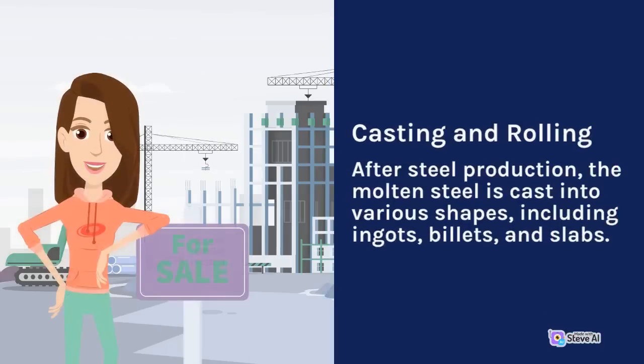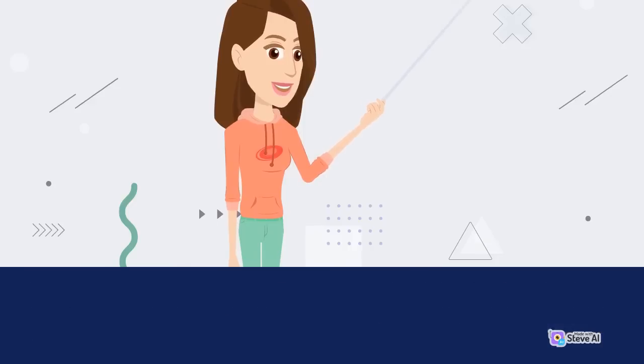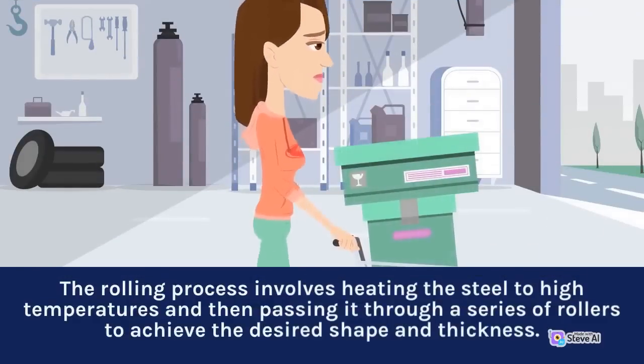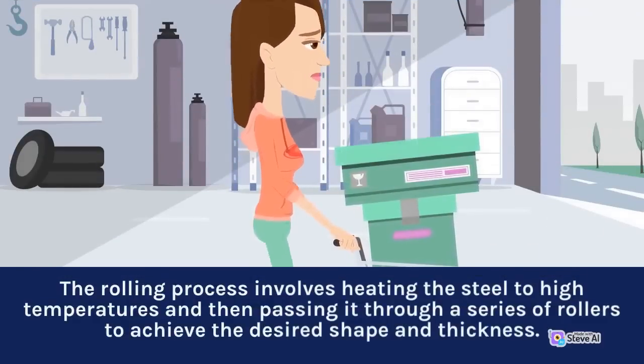Casting and rolling. After steel production, the molten steel is cast into various shapes, including ingots, billets, and slabs. These shapes are then rolled into finished products, such as sheets, bars, and pipes. The rolling process involves heating the steel to high temperatures and then passing it through a series of rollers to achieve the desired shape and thickness.